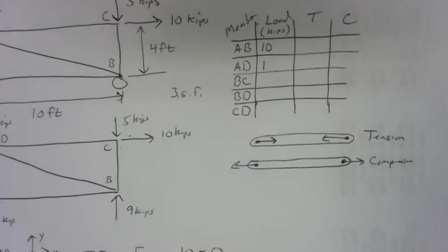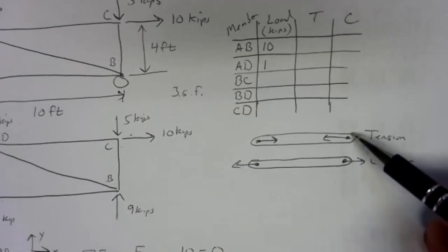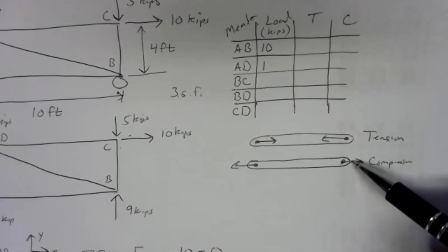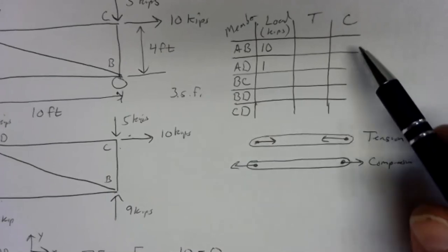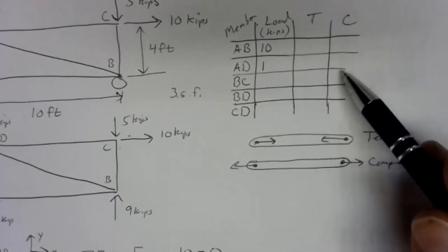If those pegs aren't strong enough, they're going to fly inward. That's what tension does to supports. Tension draws the supports inward while compression pushes the supports apart. So this will be your guide until it makes more intuitive sense to you how to look at it, how to check the boxes.